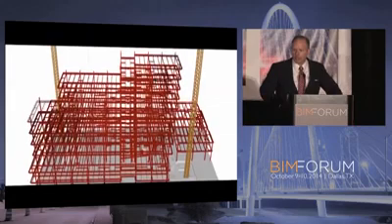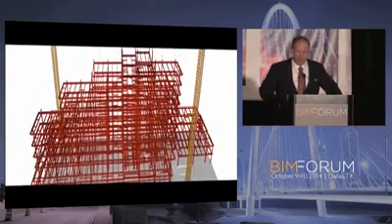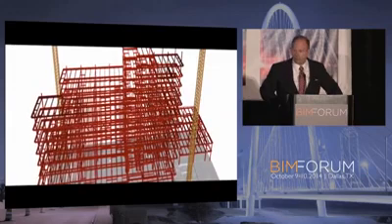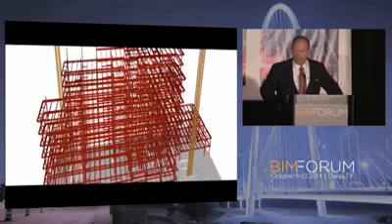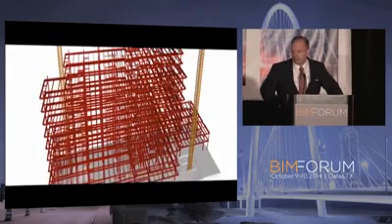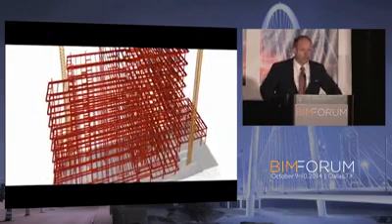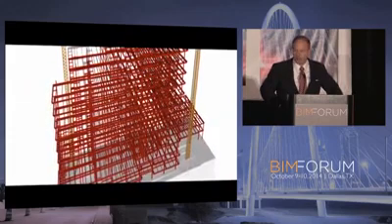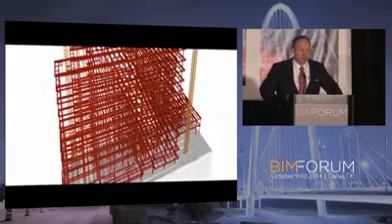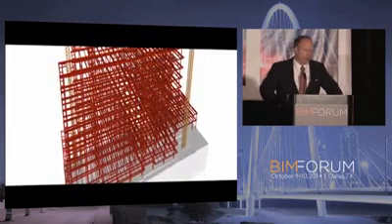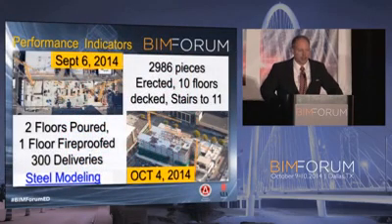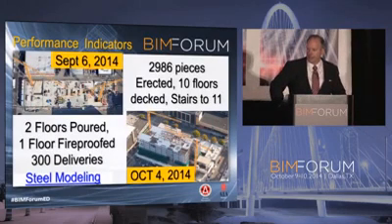In this particular project, we put the cranes in close proximity, we synchronize them, and we've been able to erect steel at twice the normal rate. In this particular project, we poured a deck 9 days after the steel had started. We're up to the 6th floor and a sister building using a single crane. When they were only to the 6th floor at 1 month, we're erected out and poured out on the 6th floor. 2,986 pieces of steel erected, 10 floors decked, stairs on all 11, 2 floors poured, 1 floor fireproofed, 300 deliveries.